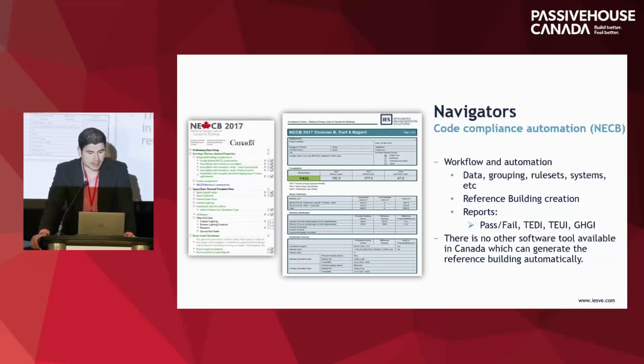One of the things that mainly differentiates us from other simulation software in the industry is that we have something called navigators. And navigators are user workflows, or guided workflows for the users, that have one objective, and that one is code compliance automation. In the case for Canada, we have been approved by NRCan to have this navigator for NECB 2011, 2015, 2017, and 2020, which is the latest code that has been adopted in some of the provinces already.